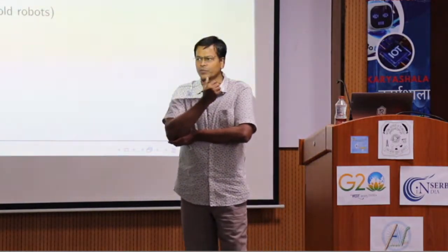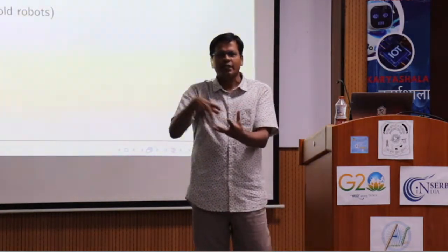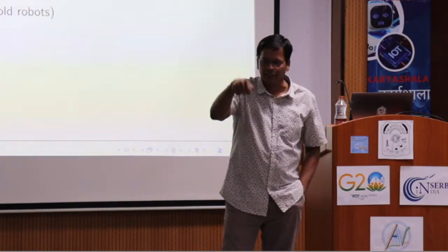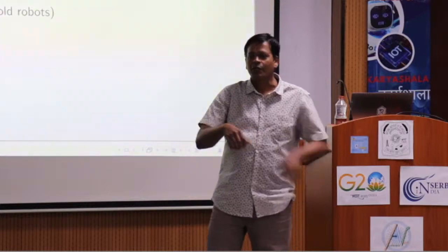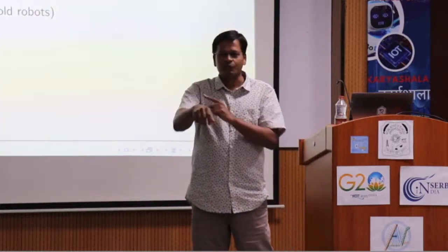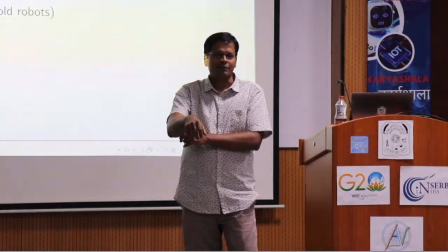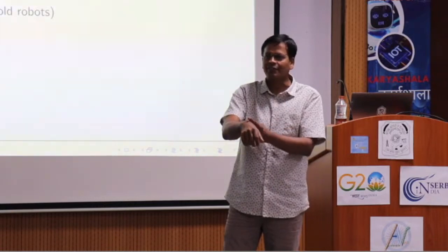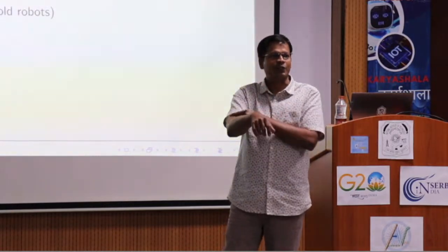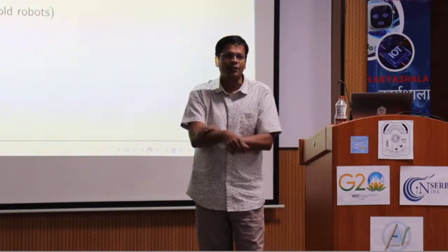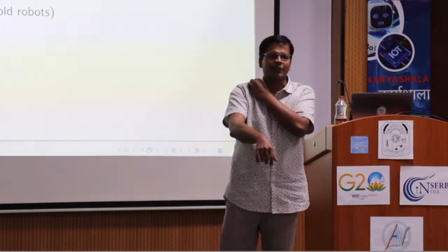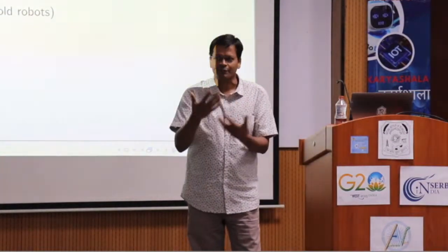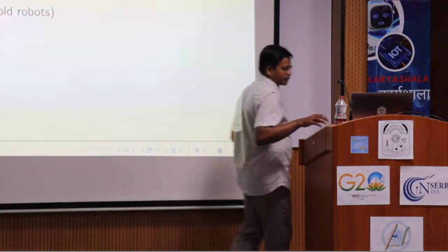The problem with the earlier robot with the end effector sensor was that it had a force sensor at the wrist. It can detect the forces, can do the force-based assembly task, but only after the wrist. If your link gets entangled anywhere, you're gone. It won't even come to know, because your sensor is sitting here, it can sense anything which is after this, not before this. So that was the problem. But with this kind of robot, you have a torque sensor at each joint. You can convert that torque to the forces that are coming in. You know the physics of it, right? So that is how it is done.